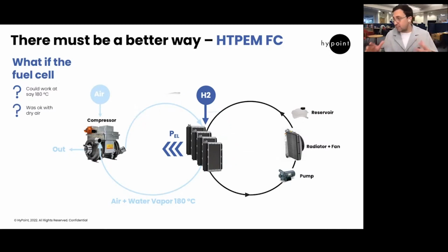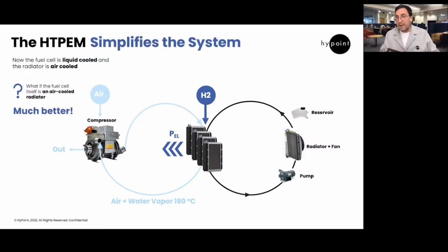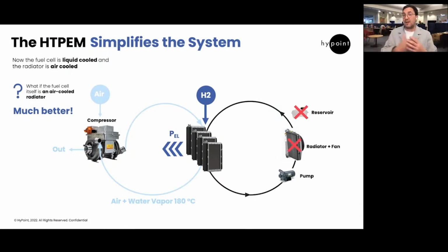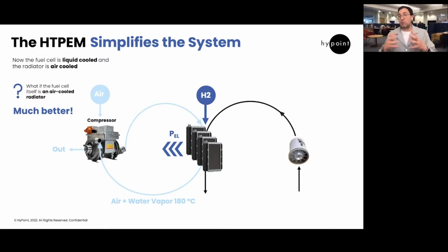And in the end, let's imagine that your fuel cell becomes a radiator itself. Our company designed lightweight aluminum bipolar plates. At the same time, it works like a bipolar plate, and at the same time, it works like a radiator. So you don't need it at all. You can exclude liquid coolant, and from the system design, you can exclude the radiator and fan. And actually, you also don't need to use a pump. So you just need to replace it with a standard fan,